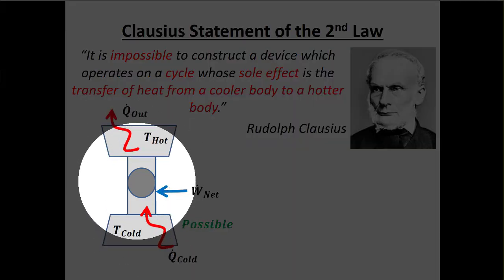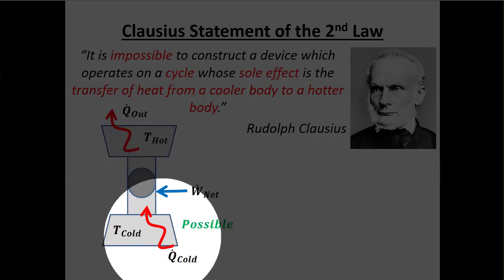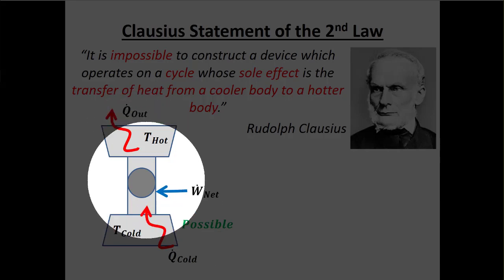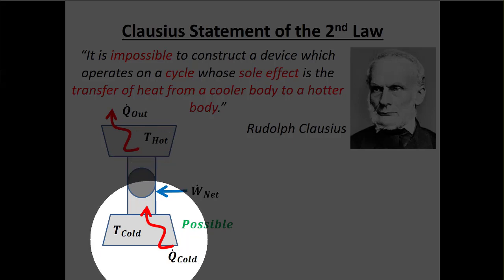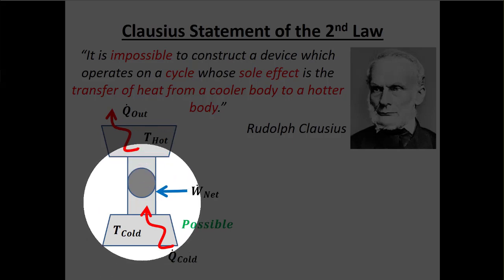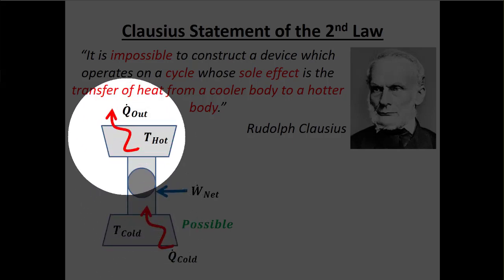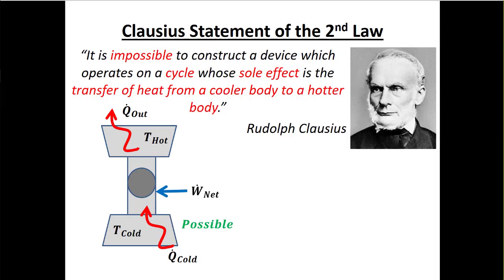And what we do, we don't actually break the universe here. We're not really transferring heat from a cold place to a hot place. Instead, we make a machine where the cold half of the machine is colder than the cold place, but then there's a hot side of the machine that's hotter than the hot place. So we're not breaking what my old heat transfer professor used to call the 0th law of thermodynamics, that heat always flows from a higher temperature to a lower temperature. We're just making a machine that has a cold side that's colder than the cold place.